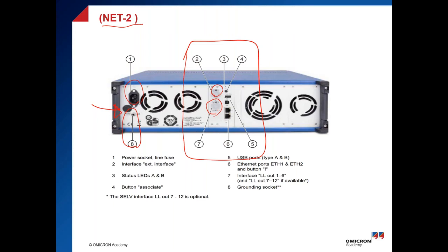non-conventional, or what we call low-level input relays, which are connected to a Rogowski coil instead of a normal conventional CT. This can be used with some accessories we offer. This is very beneficial. Instead of purchasing a new complete test kit, you can use your CMC to test that kind of protection relays.